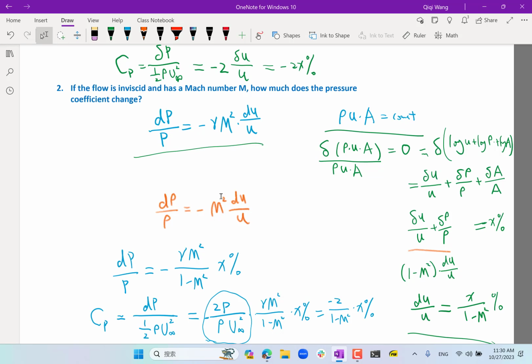Incompressible flow can be obtained essentially by looking at the fluid with baseline pressure so high that it is much higher than the aerodynamic pressure you have. As the velocity increases, the aerodynamic pressure increases, and at some point it's comparable with the baseline static pressure, and that's when you have to consider compressibility. Good question. Any other questions?